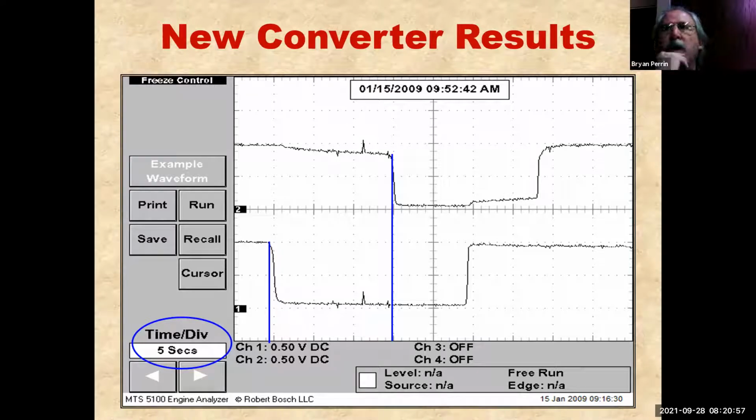On the other hand, if the new catalytic converter I put on is way better than the other bank, then I know that new converter I put on is performing awesome because I know what the computer thinks of the other bank. So this has helped me over time decide, A, what brands do I want to use? The other is it also gives me a lot of confidence that I fixed the car without having to go run the OBD2 diagnostic monitor to verify the converter passes the OBD2 monitor. Because I've already proved it's good because I've compared it to the one that the computer is happy with, if I have 2 banks on the vehicle.